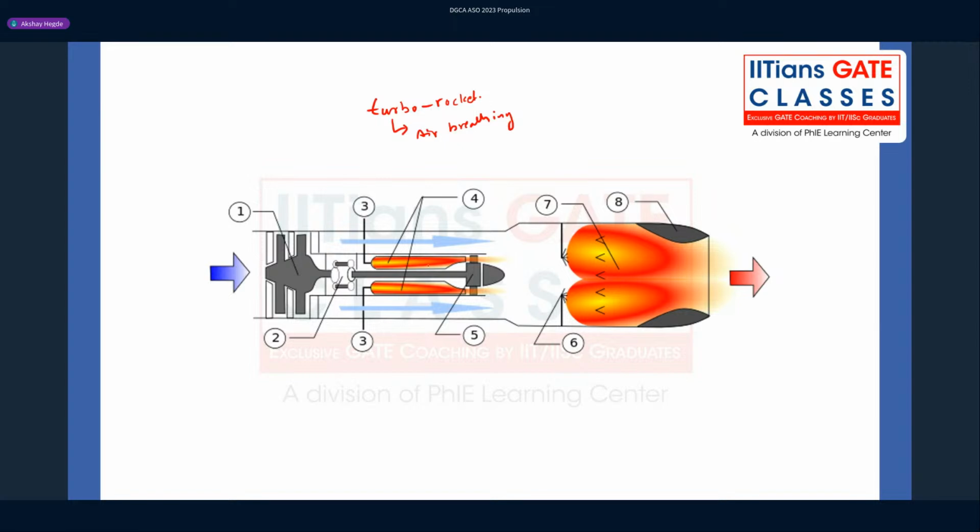So we have a turbojet that uses a set of fans or compressors that are run by a turbine, where the air is being compressed. Okay. So this compressed air is then provided to the rocket chamber where we will add extra fuel to burn the high pressurized gas, and then we will raise the enthalpy of the system and allow it through the converging diverging nozzle to produce the thrust.